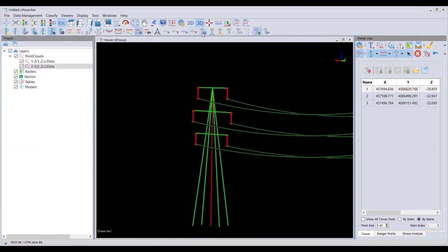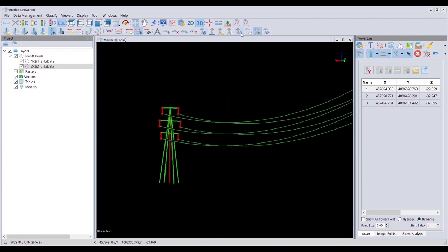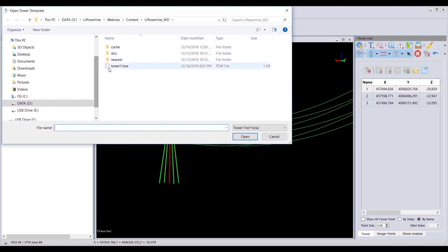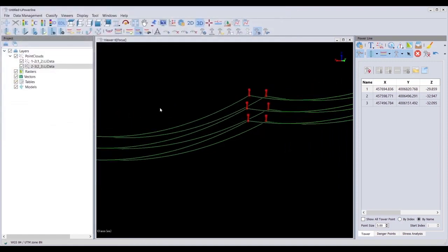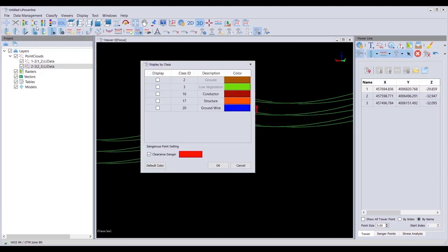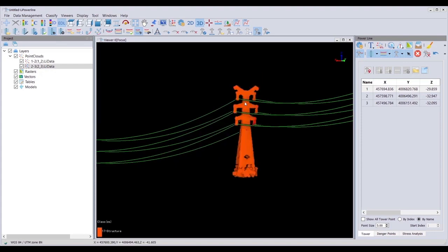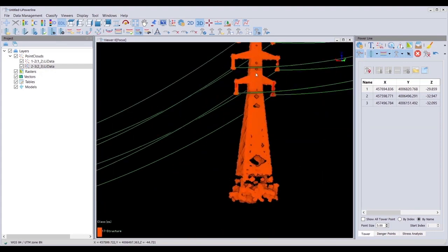I can even load it back into this demonstration and use it to vectorize other towers located in the sample dataset. I'll turn back on my structures so I see exactly where the high center point is that I'll need to place the tower object. Once again, I'll need to rotate the point cloud to find it, and this can take a little doing.